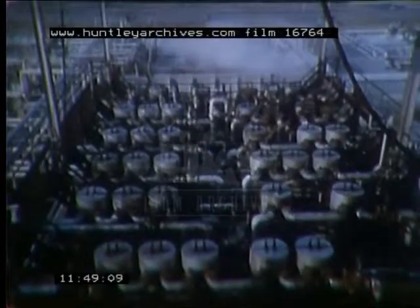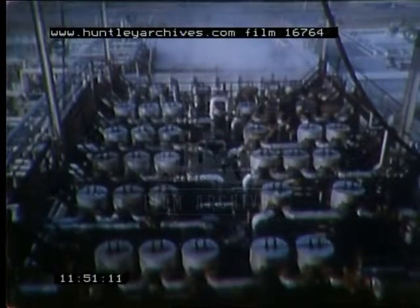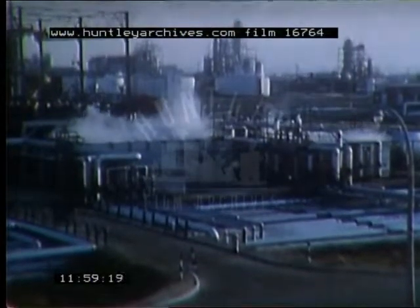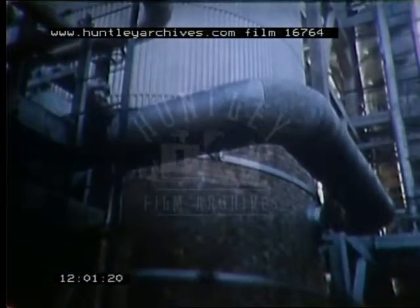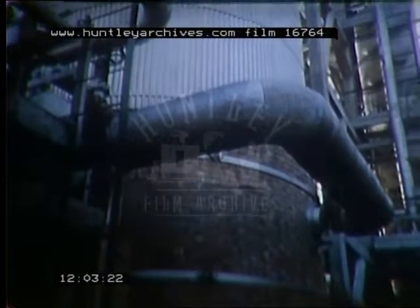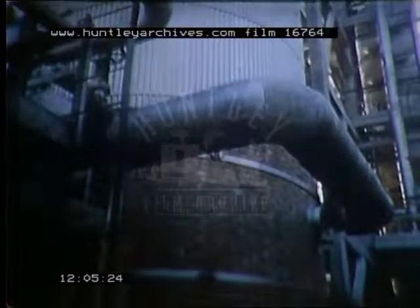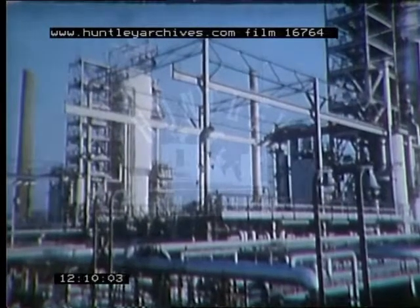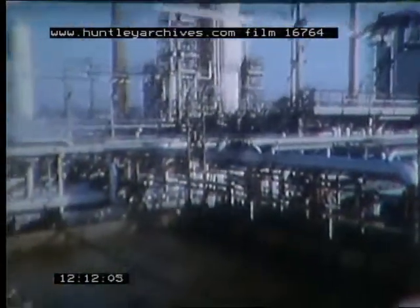Then the cuts are partly cooled in heat exchangers before being passed to a water-filled cooler tank. The stripped vacuum residue from the bottom of the stripper section of the tower again goes through heat exchangers, and if not pumped direct to the lubricating oil refinery, passes through its own cooler tank to storage.